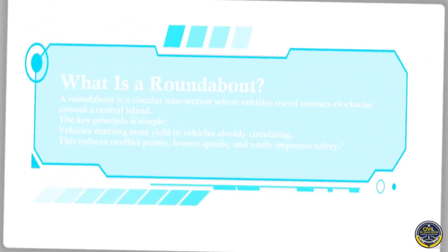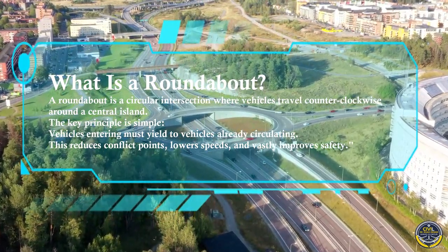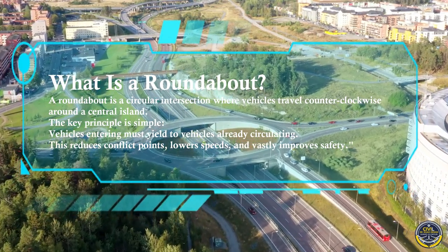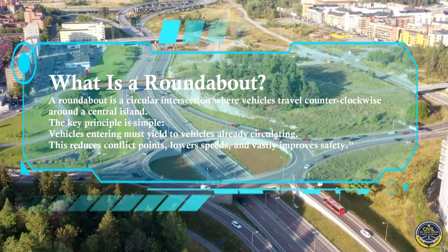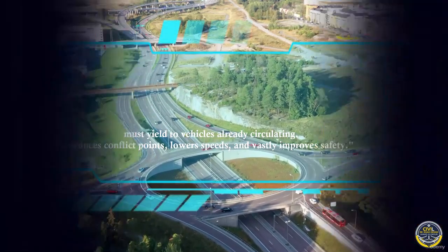What's a roundabout? A roundabout is a circular intersection where vehicles travel counterclockwise around a central island. The key principle is simple. Vehicles entering must yield to vehicles already circulating. This reduces conflict points, lowers speeds, and vastly improves safety.